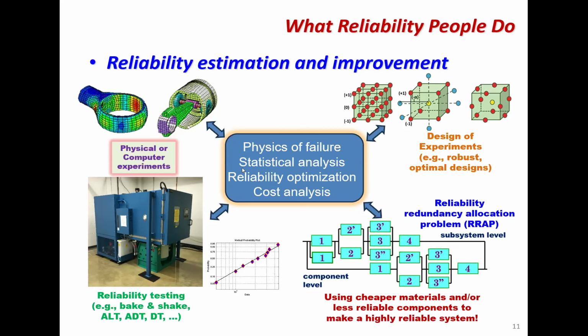And also a lot of people are testing engineers. They conduct reliability tests in the laboratory to expose the material and product to stressors, extreme environment conditions, for instance, temperature, humidity, and current, and so on, to surface those failure modes and estimate reliability based on failure time data or degradation data. And then they assemble those component-level reliability estimates together in order to estimate system reliability.